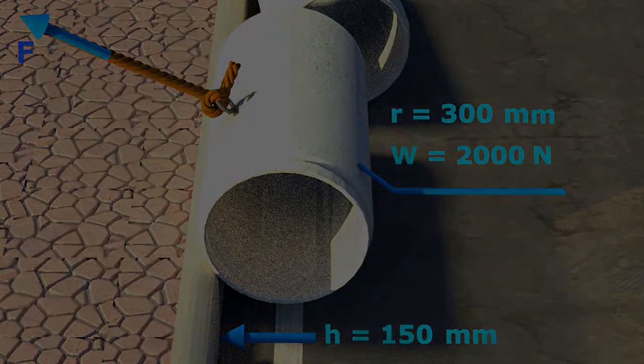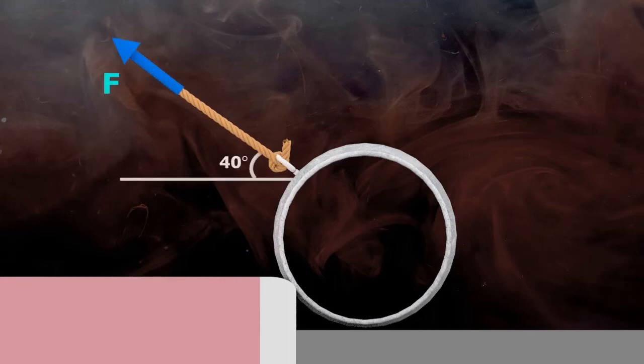To solve this numerical, we will consider the side view of pipe by taking cross-section of pavement and footpath. First step is to draw the free body diagram by considering all the forces acting on the pipe. There can be three types of forces acting on a body while in equilibrium. One is external force applied. In our case, external force F is acting on pipe making 40° angle to x-axis and it will pass through the center of gravity of cylinder if extended.